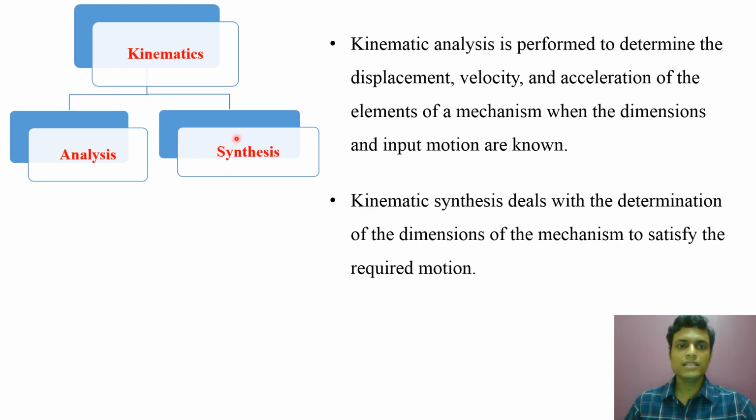Whereas synthesis is completely opposite to kinematic analysis. Kinematic synthesis deals with the determination of the dimensions of mechanism to satisfy the required motion. That means the required motion is known to us. We have to select proper dimensions of links and other elements.